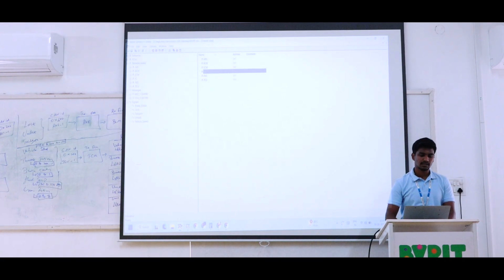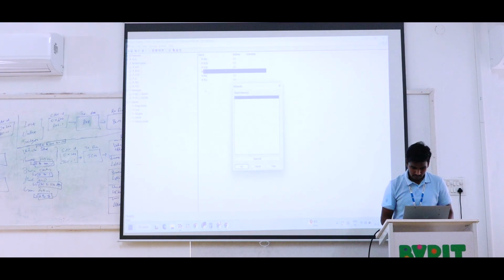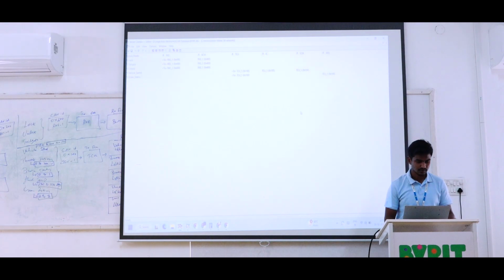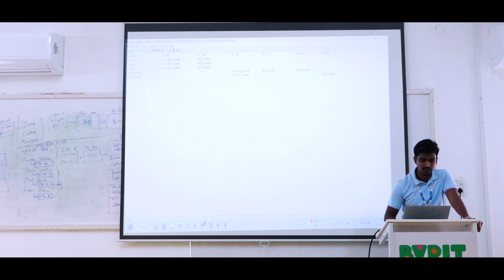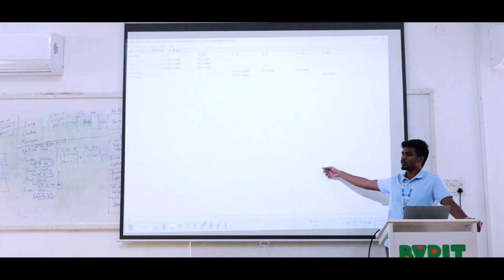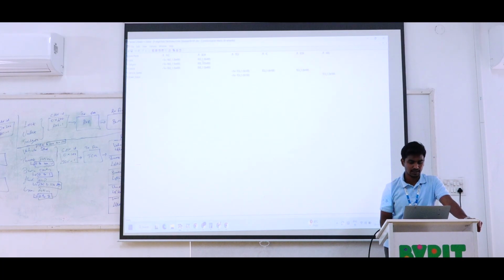Okay. So now we can see it in our communication matrix view. Here you can see that previously we did lock and tailgate unlock. It is transmitted by the RKE ECU, and there is no need to specify any other ECUs. It is received only by the body control module ECU.